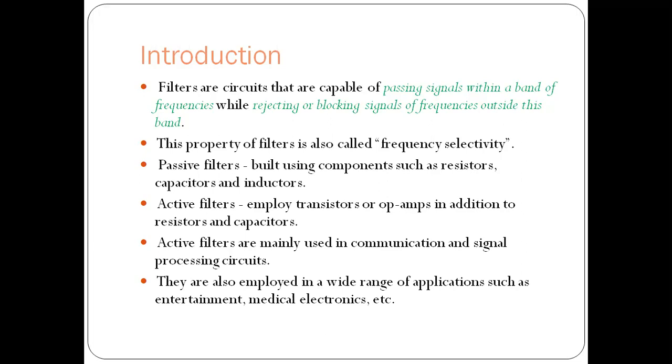Also, an opamp can operate in two modes: non-inverting mode as well as inverting mode. An opamp has the advantage that it provides high gain, and attenuation will be less. The opamp used here is in non-inverting configuration. The non-inverting configuration offers a high input impedance and low output impedance, which improves the load drive capacity. That means it can drive the load and is isolated from other networks, other circuits.